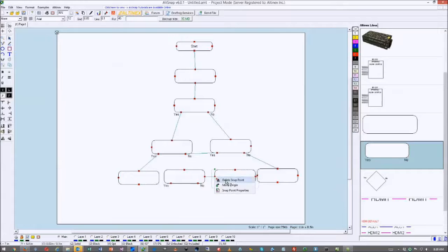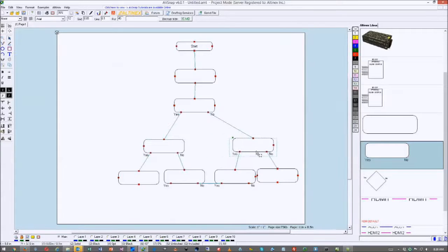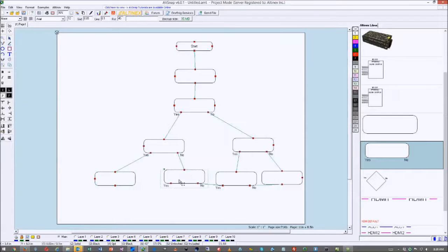And it will recalculate how things need to be connected, okay? Now, it always does it by the proximity. So if these two points are closer to each other, it will connect it. So if you want this point connected to the bottom portion of it, just move this aside just a little bit right there. And the same thing here, just move it a little bit aside. These ones you may want to delete snap point here, delete snap point. And the same thing, you can move this.